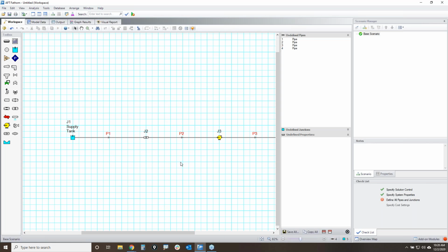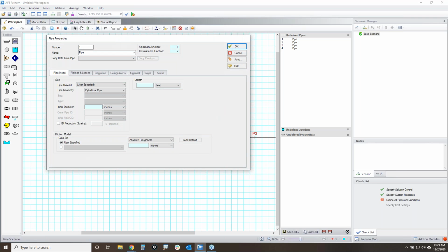Now, if I click and drag from right to left, the box is yellow. This is going to select anything completely in the box or crossing the boundaries of the box. So notice how it grabbed the two additional pipes for me. So a lot of times when I try to select pipes, I'll just click and drag a little bit over that pipe like this and select it, and then hit enter on my keyboard, and that opens it up a little bit easier for me.